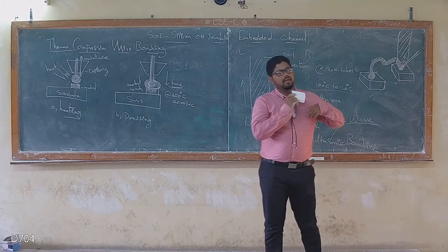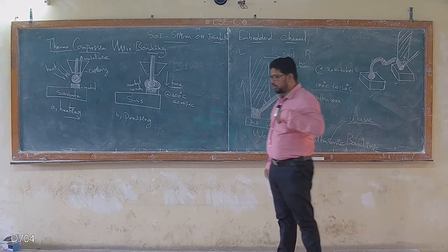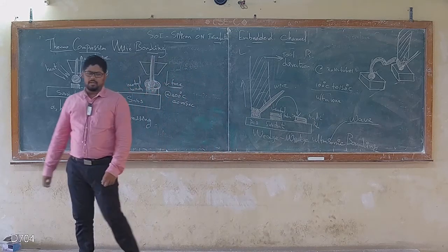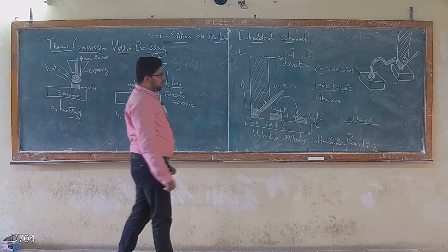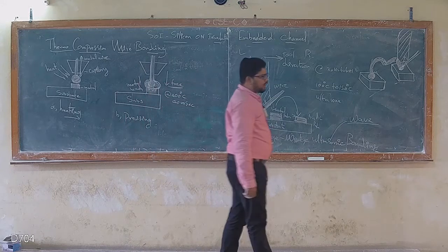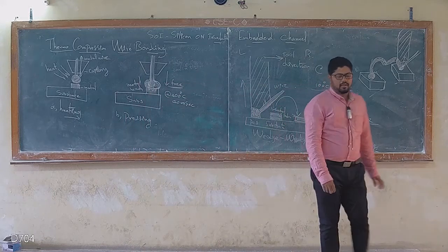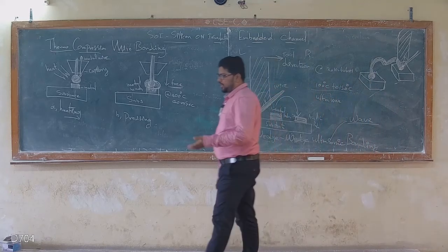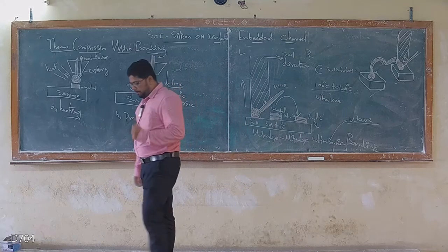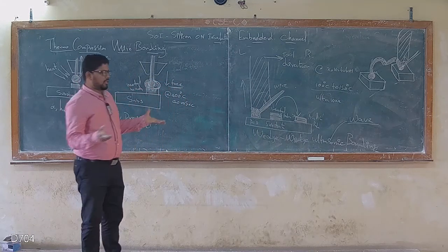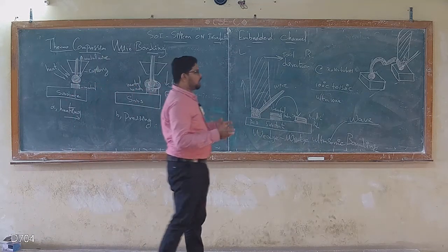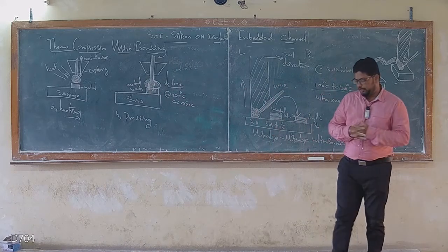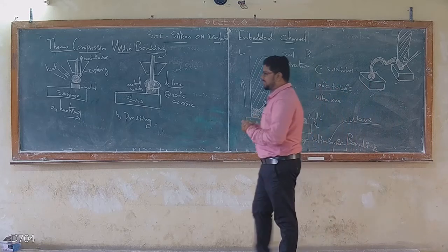Tomorrow we will see what we mean by encapsulation and what we mean by sealing, right? Encapsulation is the technique where we could isolate the die. Die is a complete electronic chip, which we could isolate from the other circuit by making either a plastic mold or non-conductive molding, right? It's called encapsulation. Then the second word is sealing.